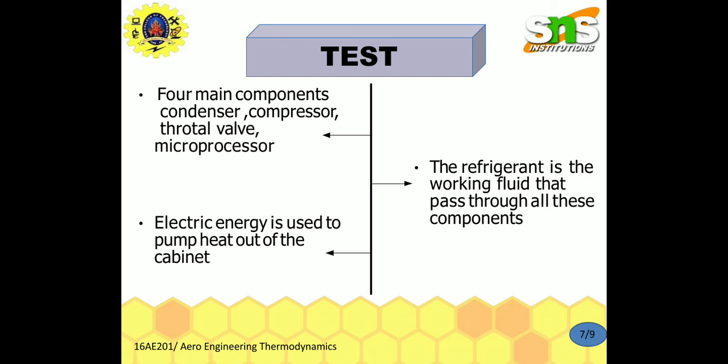This implies that the COP of a heat pump will be greater than 1, because the COP of a refrigerator is a positive quantity. In a worst-case scenario, the heat pump will supply as much energy as it consumes, making it act as a resistance heater. However, in reality, as in home heating, some of the heat is lost to the outside air through the pipes and insulation, thus making the COP of the heat pump drop below unity when the outside air temperature is too low. Therefore, in such cases the system is used to heat houses using fuel.